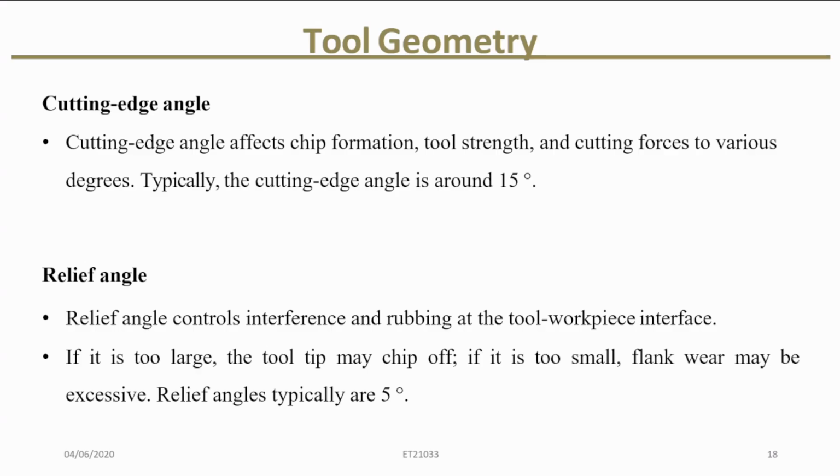When we consider the relief angle, relief prevents the flank from rubbing the fresh surface. If it is too small, the flank wears.